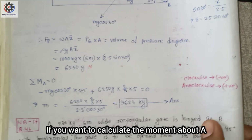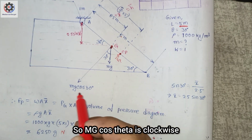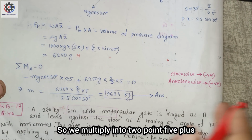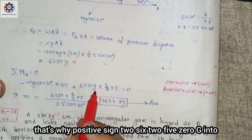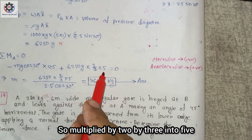Okay, now if you want to calculate the moment about A, that is equal to 0. So here mg cos theta is acting in the clockwise direction, that's why negative. Mg cos 30 degree into what is this height, that is 2.5. So multiplied into 2.5, plus the pressure force that is acting anti-clockwise, that's why positive sign, 26250 g into, and what is this height? So here 2 by 3 into 5. So multiplied by 2 by 3 into 5, that is equal to 0.